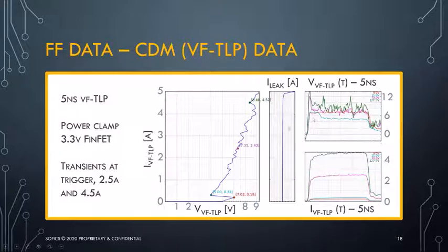And then for the higher current stress levels, you can actually see some overshoot in a very short window of time. That is not problematic. Actually, as it is tested with a parallel gate oxide, we have experimental proof that it's non-problematic. But it shows, and it's a very important curve to look at, that the overshoot in terms of voltage versus time is really limited and that the triggering happens very, very fast.